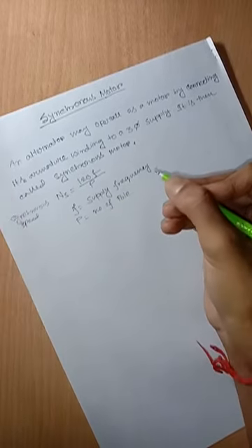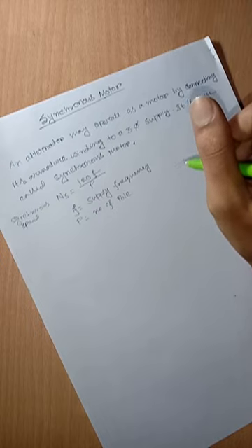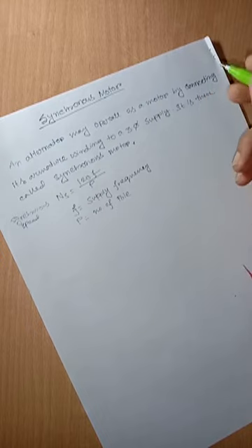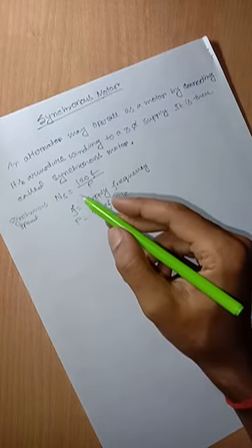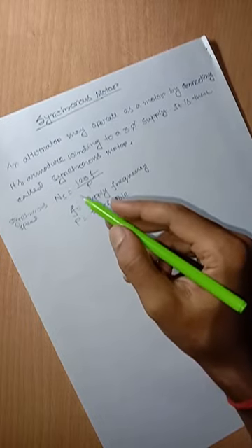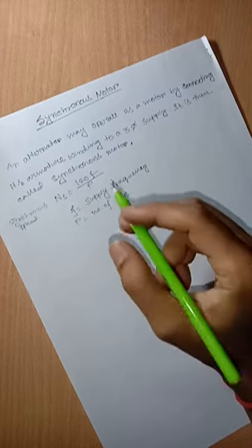and P is the number of poles. So in case of a synchronous motor, the frequency is constant, so the speed of rotation is tied to the frequency of the source. Since the frequency is fixed, the motor speed stays constant irrespective of the load or over-voltage of the three-phase supply.